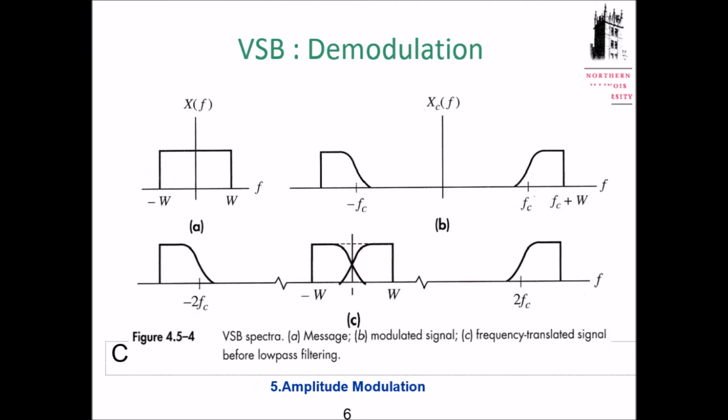So using the vestigial sideband, if you look at your modulated signal, it does not look like your original message at all. However, when we do the reconstruction or demodulation, your original signal is reconstructed. So the tricky thing is the filter shape. And we know this one looks like maybe second order or third order, but it's filtered much easier compared with the ideal or very high accuracy low pass filter.